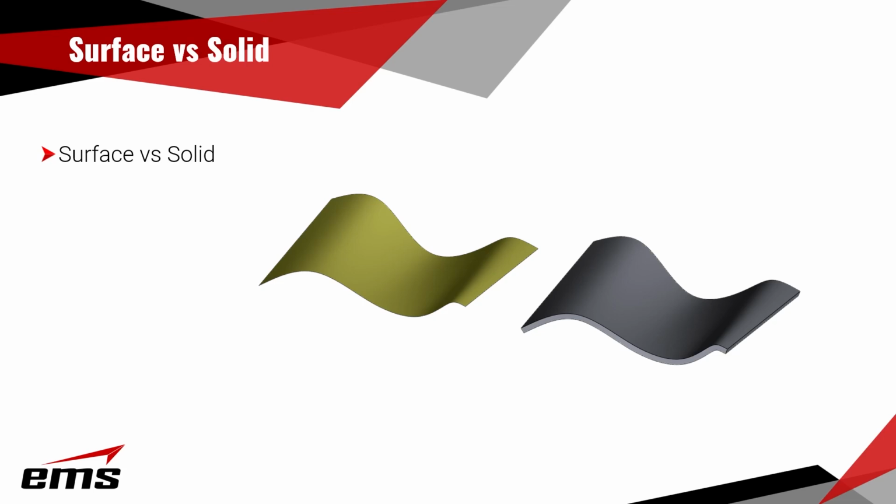Now, the words surface and solid, if you use a 3D CAD system, those are pretty general terms to describe things, but they may not have the same meaning to everybody. So I'm going to define what we're generally talking about here in this video. When we're talking about a surface, what you see on the left is what we would mean. It really means something that has no thickness to it. It might be a very organic shape, but we also refer to them as skins. Some people call them skins. So it really has no mathematical thickness. It's just some shape. And generally, why you would use this is because it has a lot of free-flowing shape to it.